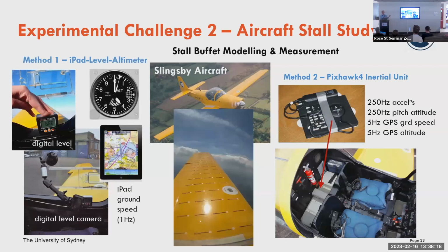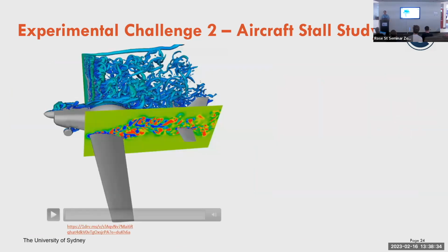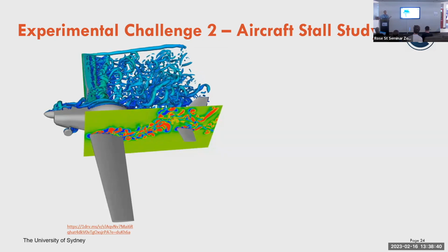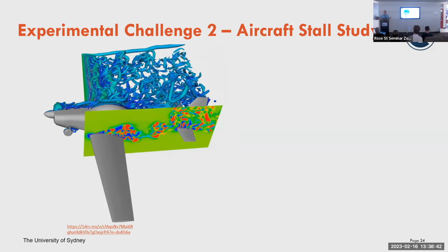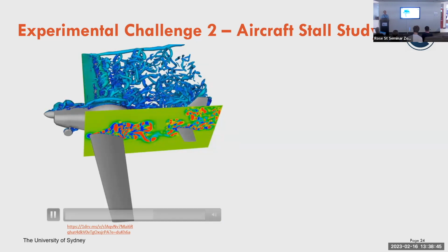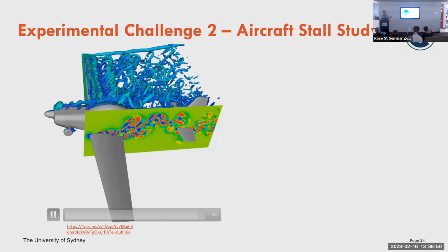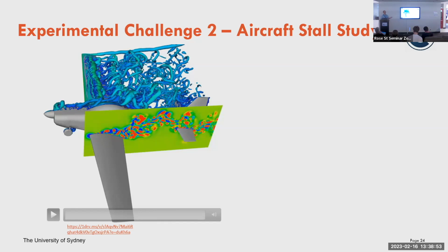We had a number of bits of different equipment in, some accelerometers, usual standard equipment in the aircraft like altimeters, and we were measuring a whole load of data during the stall. And during the stall, you get unsteady buffeting on the aircraft. Maybe these will work. Yeah. So we also did a CFD model, and this showed the same kind of result with the buffeting. There's a distinct buffeting frequency which we were picking up because you get this wake interaction with the tailplane, which the CFD predicted quite well. And the experimental data was comparing quite well to it as well.